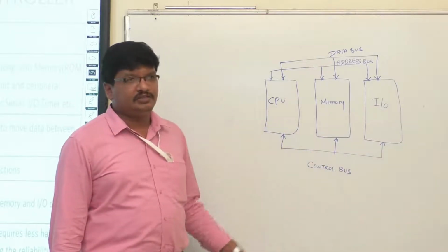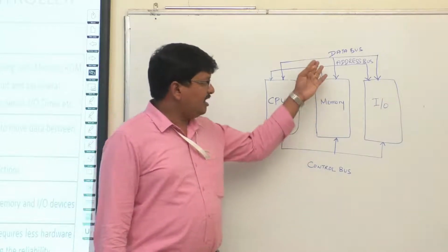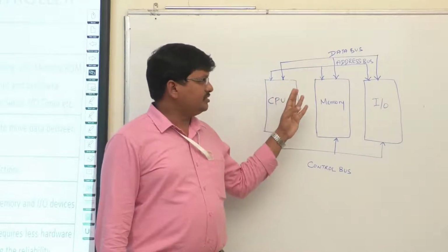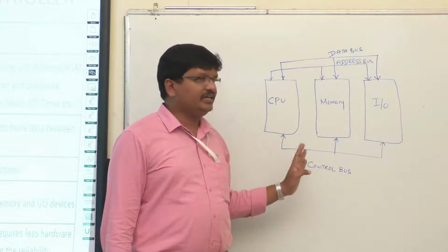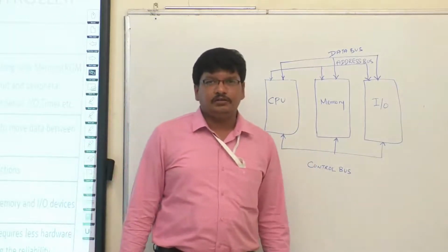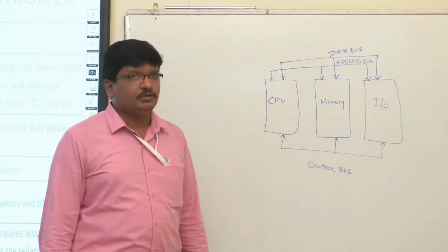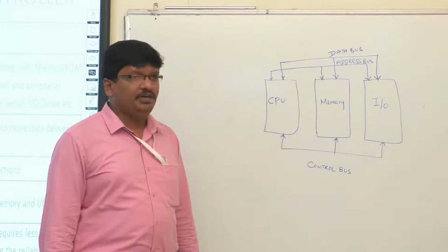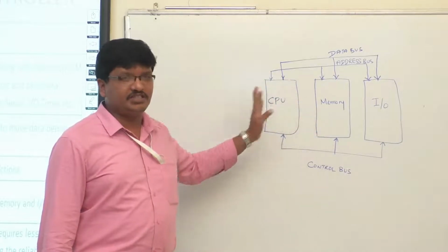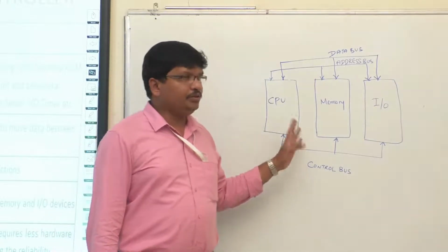Between the modules, the exchange of data takes place through these buses. As address bus, address can be shared between the modules. Data bus, data can be transferred, and control bus is used for taking care of the entire operation of the systems. We have discussed earlier that the 8085 requires more instructions that can be transferred between the memory and the CPU. So there can be more data exchanges, and more instructions are available that can be communicated between the CPU and the memory through this process.